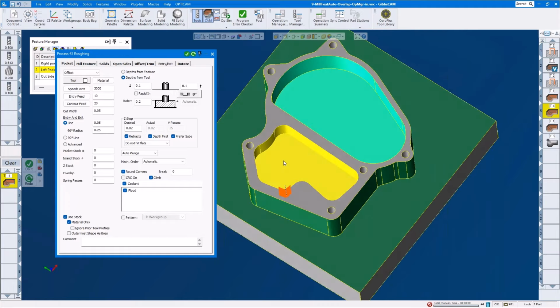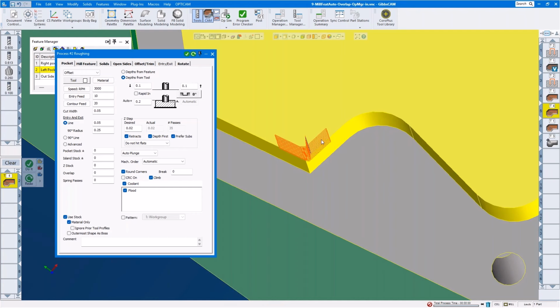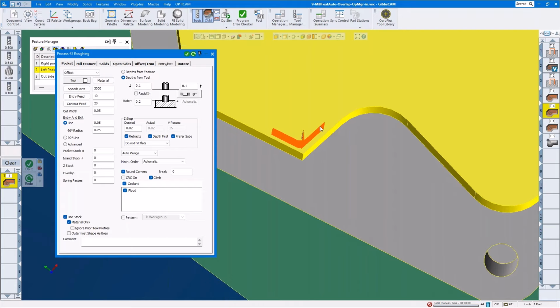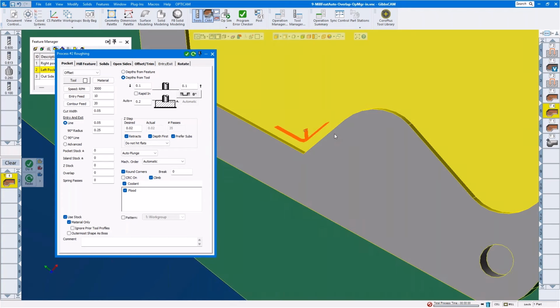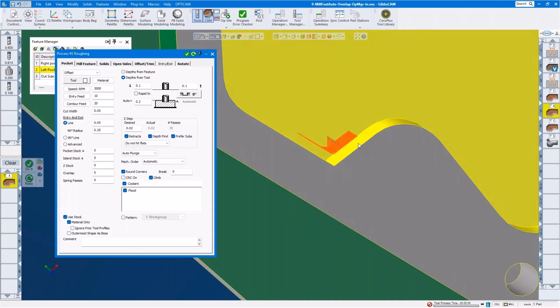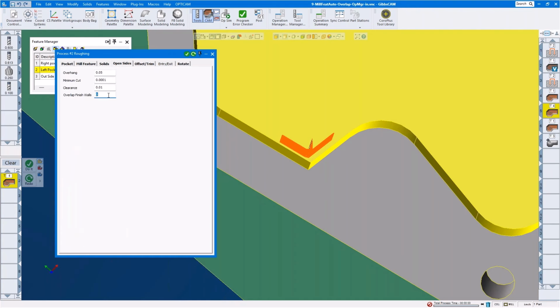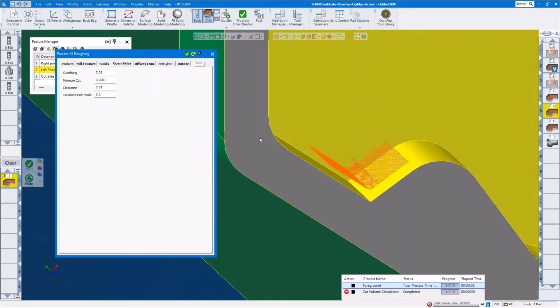Also here we have a material only. And so it's just grabbing leftover material in this corner, and this may be technically accurate, but we could be just getting the tiniest of a tool mark right here where it's blending with already machined, and we have a reason that we just need to pull that out, or maybe we want to bring it all the way to this before this curved portion. So now in open sides, we can adjust that simply with that one value. And now you can see that's been extended.